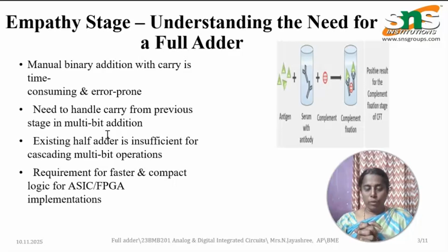The existing half adder is insufficient for cascading multi-bit operations. The half adder has only two inputs and two outputs, whereas the full adder has three inputs and two outputs. To overcome the limitation of the half adder, we are going for the full adder.